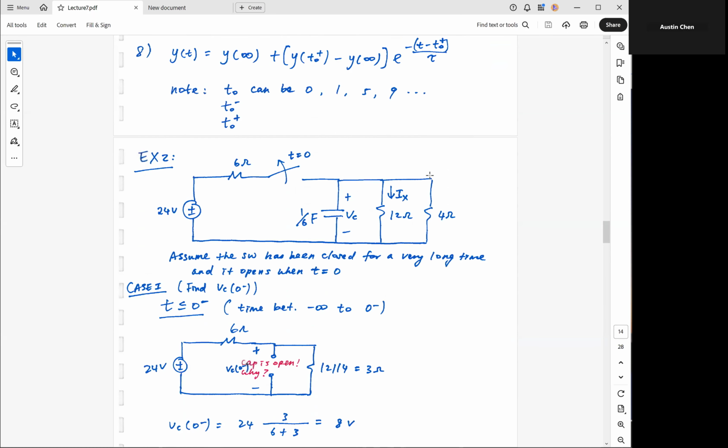how it looks like. So in general, for this type of first order RC and RL circuit problems, what's usually involved is that you will need to have some switch somewhere in your circuit to emulate this switching event as we discussed earlier. So we need to understand first whether the switch is closed or open at the switching instant.